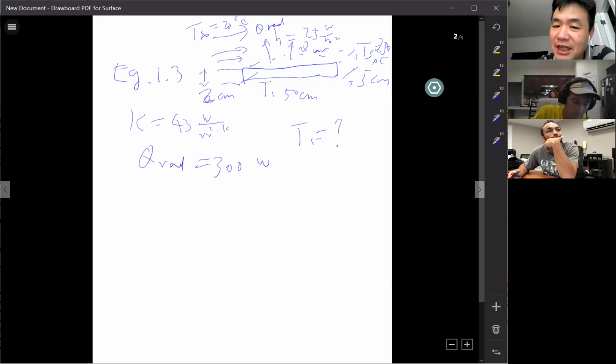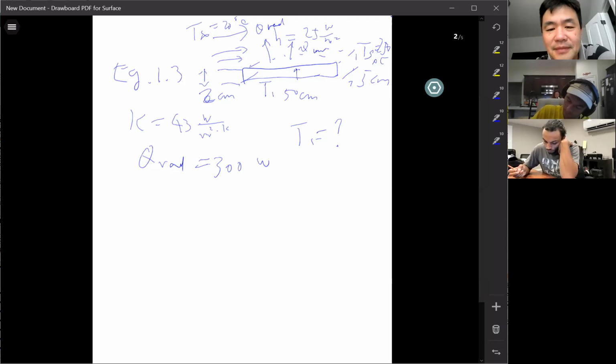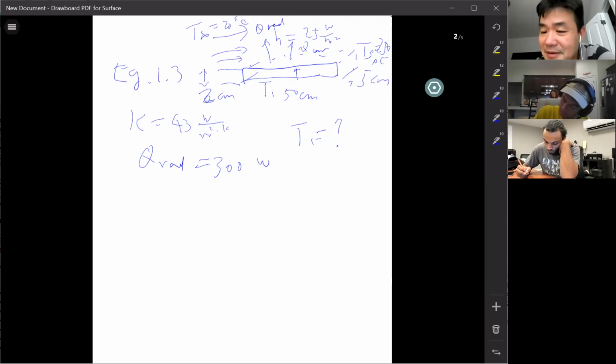One side of the surface has heat going out, the other side has to have heat going in. So the conduction inside the plate must go this way. If the conduction is in this direction, the other side of the surface has to be at a higher temperature, has to be hotter. Then the heat transfer by conduction goes from hot to cooler.